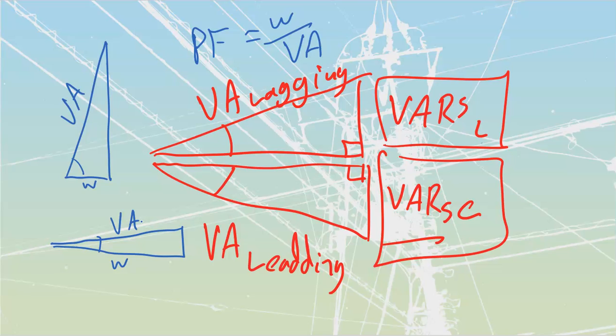good power factor. The book also goes over how we can correct, right? We can take any sort of power factor, whatever we have, that's made up of my watts and my vars, and then I can take and collapse that hypotenuse back in onto the watts itself. How do I do that? Well, I would do that by taking out the vars. The way that we take out vars is we just add in vars of the opposite type. Remember that nature tends to want to go in balance, that we are going to have inductance and capacitance that are seen in opposition to each other and able to cancel each other's effects.